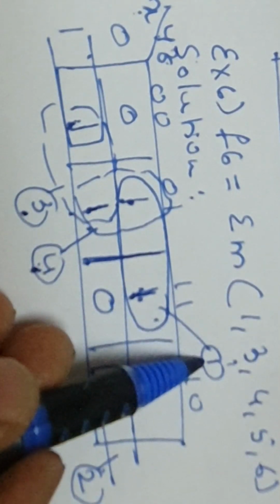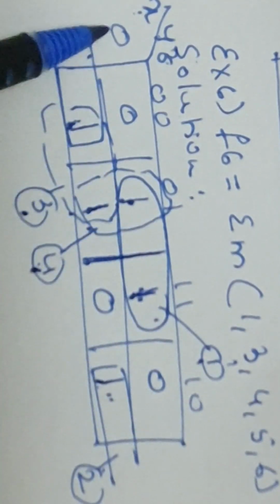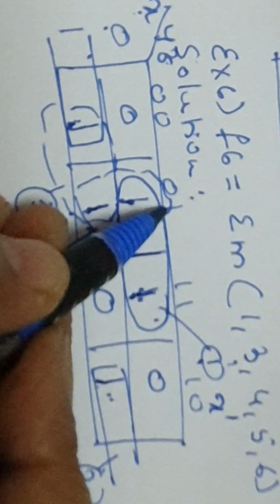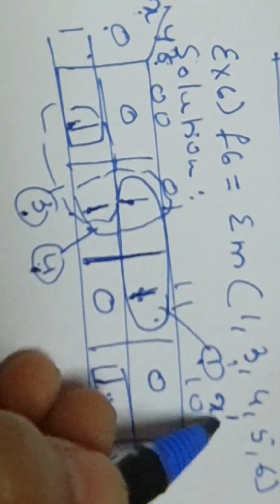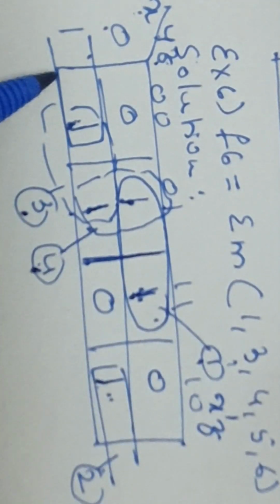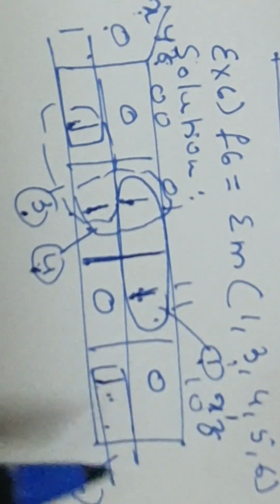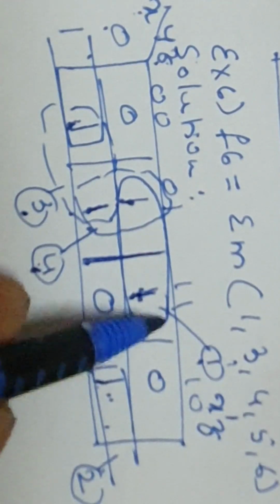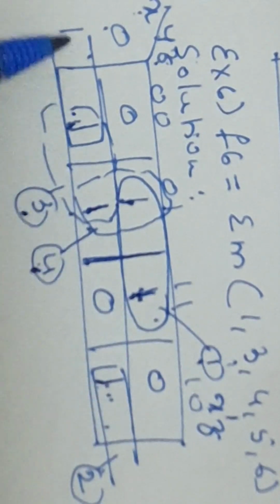Okay. With respect to group 1, what can we write here? Prime implicant, these two. Here x is 0, so x dash is common. These two ones fall in these columns, 0 1 is there, 1 1 is there. This 1 is common. This 1 corresponds to z. So it is x dash z. Then this is an essential prime implicant, because this 1 is there which is covered only in this group.